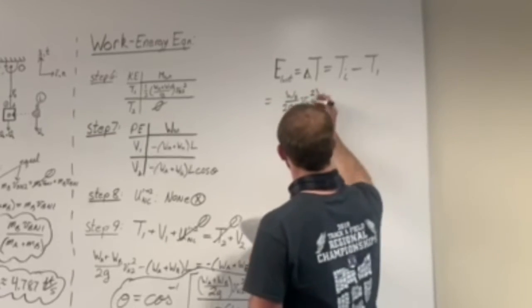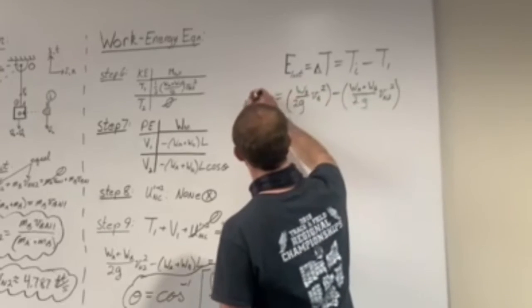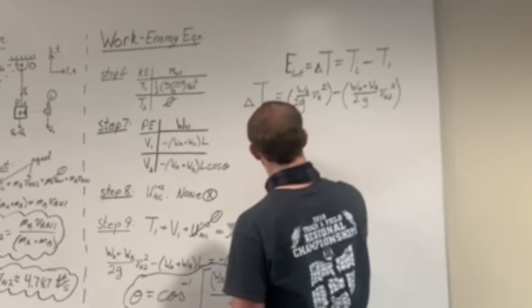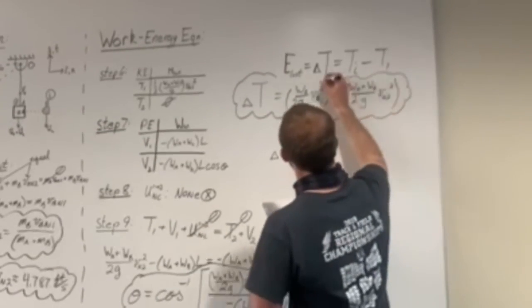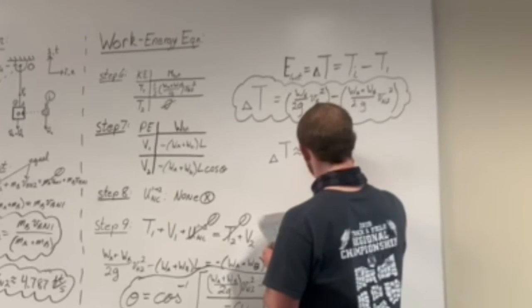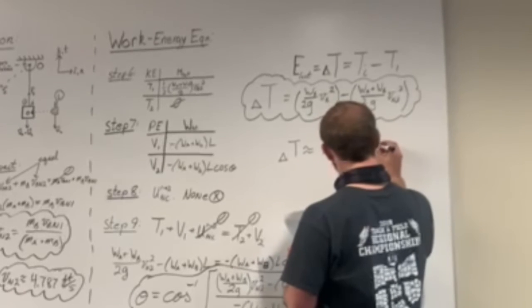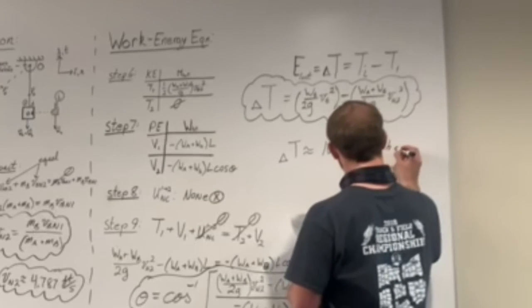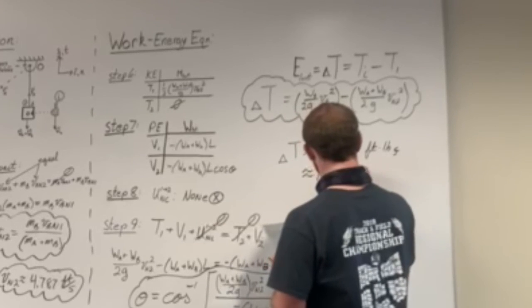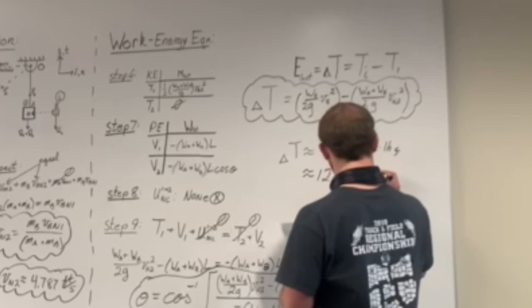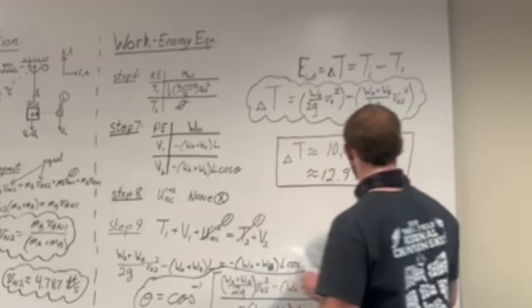So that is the equation we got for our change in kinetic energy. Then when we solve for this, we get approximately 10,043 foot-pounds force. Or, converting to thermal units, we got 12.9 BTUs. And that's going to be your energy loss due to the impact.